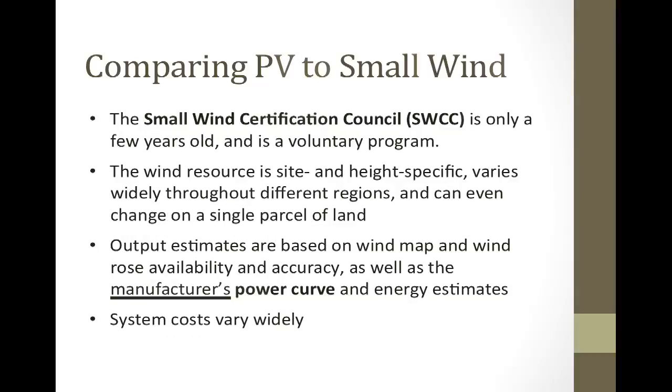So the SWCC, it's not a very old program. It's only been around for a little while. It's a voluntary program. Well, we say it's voluntary, but now that the NEC says it, your turbine has to be on the system. It has to be listed by the SWCC, or at least meet the standards listed by the SWCC. So it's soon going to be a non-voluntary program. If you want to put your turbine on the grid, it has to meet these standards, and this is the only outfit that's going to measure whether the standards can be met or not.